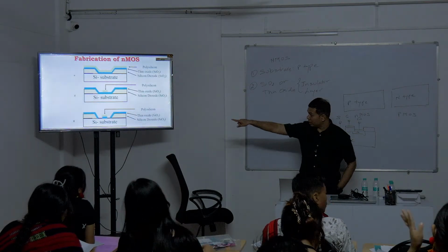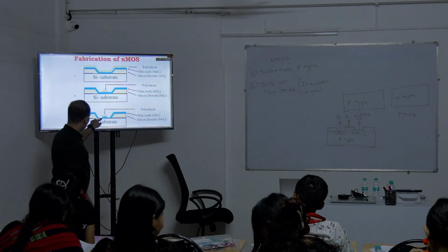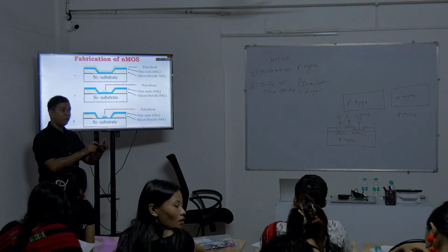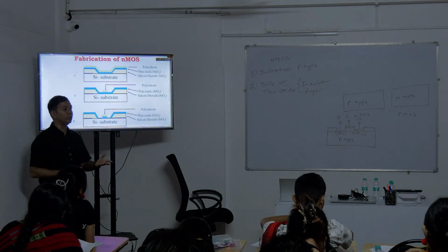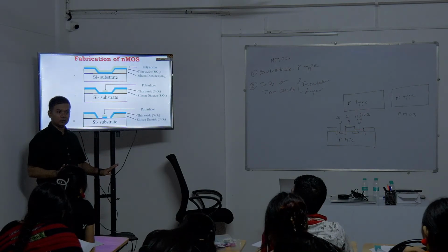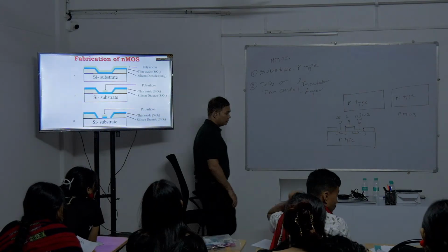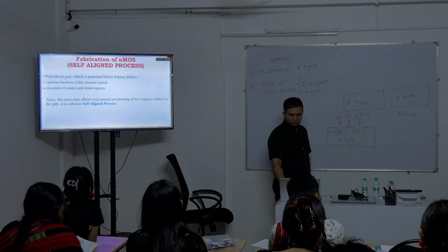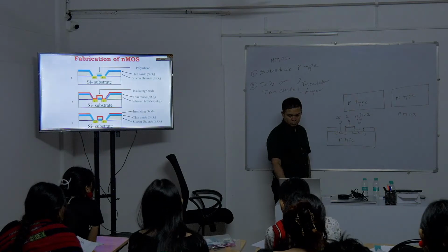For the different layers that you see in different colors, you need to follow the photolithography process at every layer. Wherever you want to keep that layer, you need to select which particular photoresist to utilize. Hope you're understanding this now, right? So this process is done multiple times. We have a mask for the first layer, a different mask for the second layer, a third mask for the third layer.